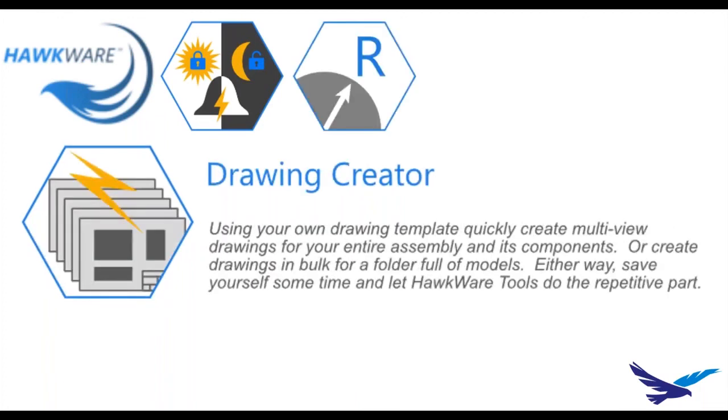So if you have a really good drawing template that has predefined views and you've annotated your model correctly, you can tell the drawing creator to make a drawing file for every part within an assembly, or maybe every file in a folder, something like that. And it'll use that template and pump out some pretty good drawings. And you just got to go in there and tweak them a bit, saving you a whole bunch of steps.